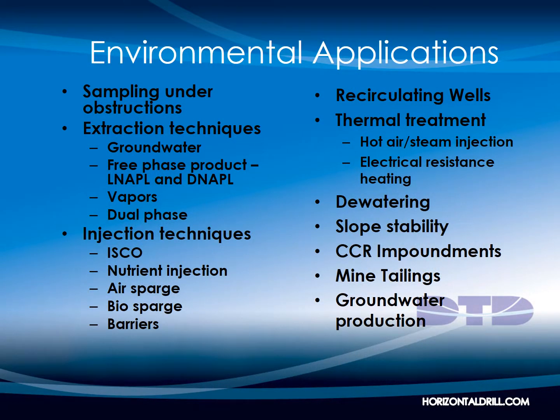Horizontal wells are used for a wide variety of remediation solutions, including soil sampling, extraction of subsurface contaminants, and injection applications. Lately, we've seen a significant increase in the completion of horizontal injection wells. These wells can be utilized for the injection of air or any other substrate used for remediation solutions.